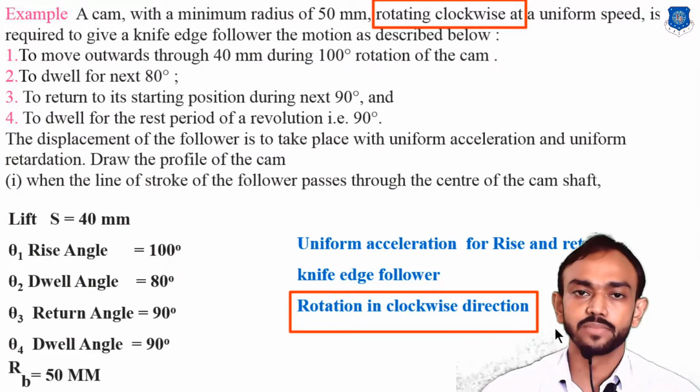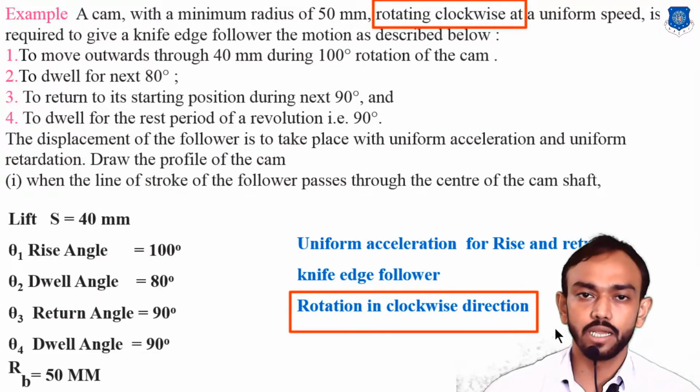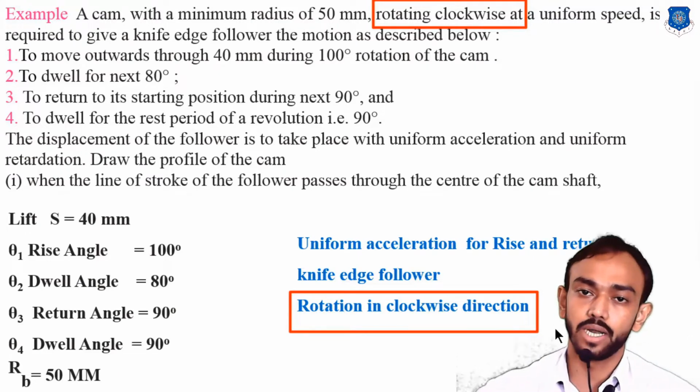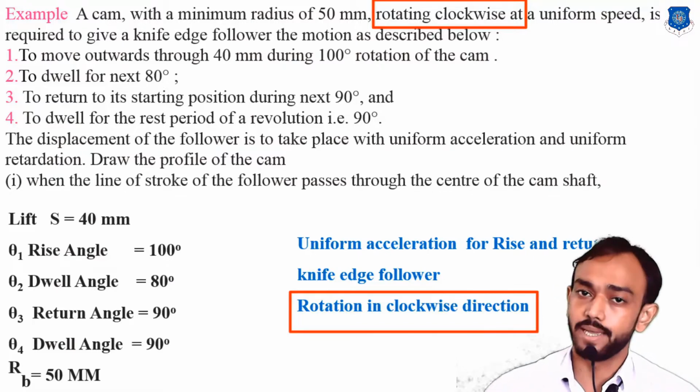Remember that if the cam is rotating in a clockwise direction, our cam profile we will draw in an anti-clockwise direction. Why? When I start the cam profile, I will show you how it works and why we take the opposite direction in a cam profile. So remember that whatever direction is given, we draw the opposite direction for the cam profile.